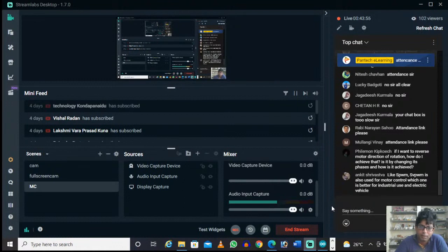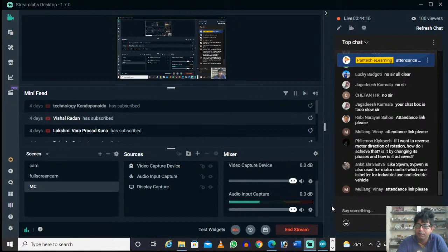For operating, when you are operating, in the drive also one digital input is there. If you remember yesterday's class, forward and reverse, in the drive I am using one contact. If the 24 volt is going to that Li1, it will start to rotate forward for 2 wire control. And if it is connected to another, Li2, it will start to rotate reverse.